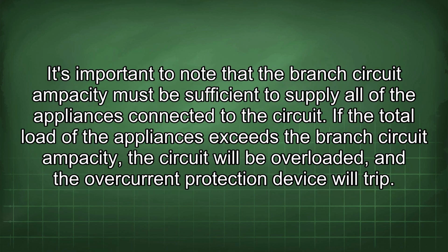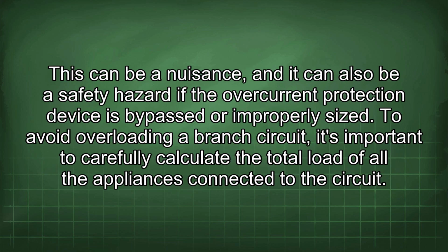It's important to note that the branch circuit ampacity must be sufficient to supply all of the appliances connected to the circuit. If the total load of the appliances exceeds the branch circuit ampacity, the circuit will be overloaded, and the overcurrent protection device will trip.